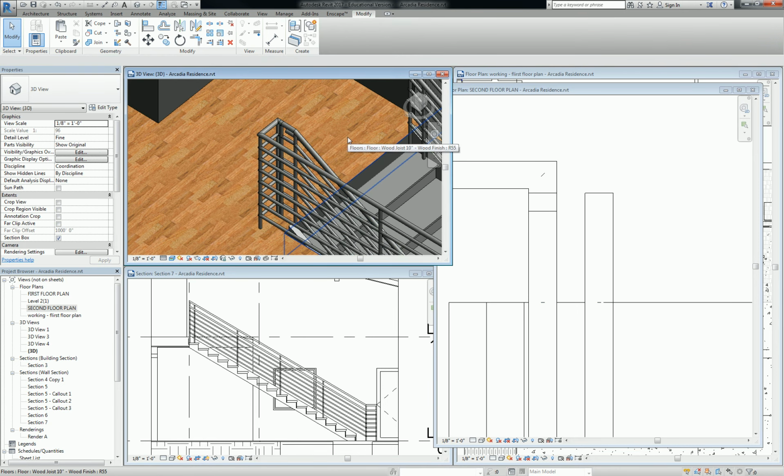You do. Yeah, you do. But if you're getting into that level of complexity and accuracy, I'd actually suggest Dynamo, which is like the Grasshopper of Revit, because you can create this parametric family with exactly the same parametric conditions and relationships that you desire. So it's a little bit smarter than using these railings, and for a level of BIM accuracy where you're actually doing quantity takeoffs of how many balusters you have, you're going to want to use something like that anyway.